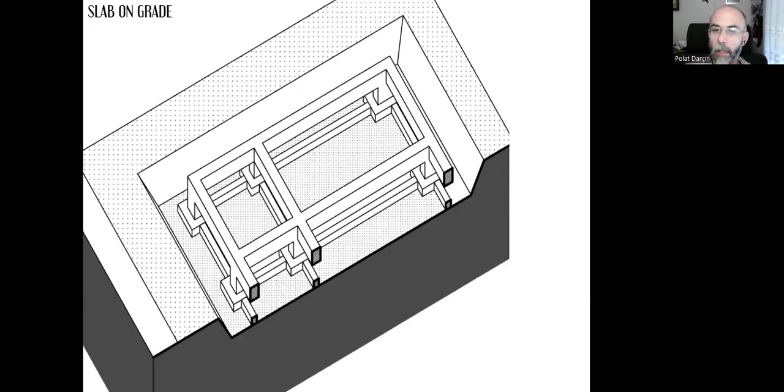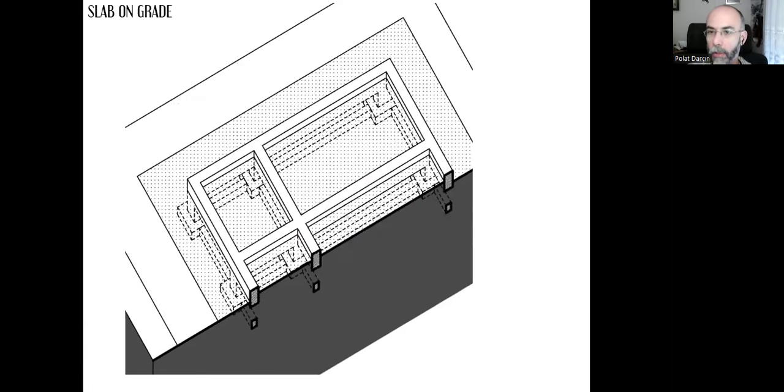Here, that's our foundation. It's completed. We are at the grade level now. And the first thing that we need to do is put all the earth back and bury the components, both inside the building area and outside the area. So there won't be any excavation gaps.